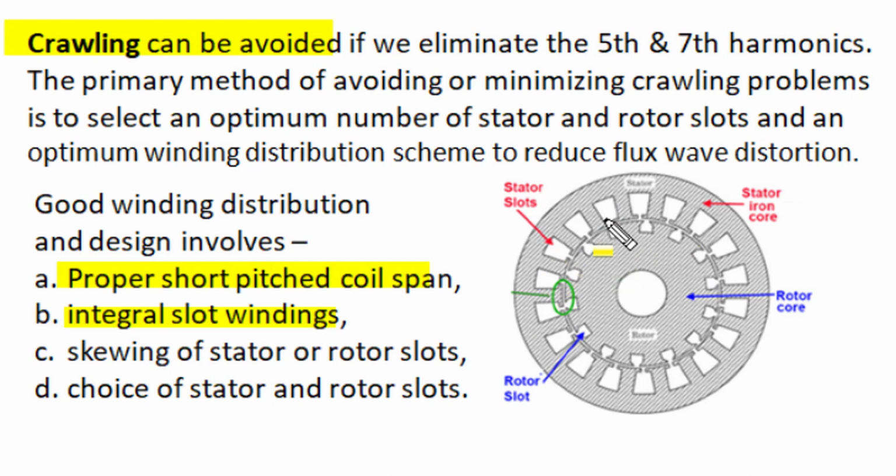With that, all poles of the 3 phases become symmetrical to each other, and a balanced time displaced excitation produces a sinusoidal air gap MMF distribution, and avoids or eliminates 5th and 7th space harmonics in the MMF wave. Skewing of rotor slots with stator slots reduces harmonics, and proper choice of the number of slots in stator and rotor also results in elimination of 5th and 7th harmonics. Proper optimum selection of stator and rotor slots is also explained here.